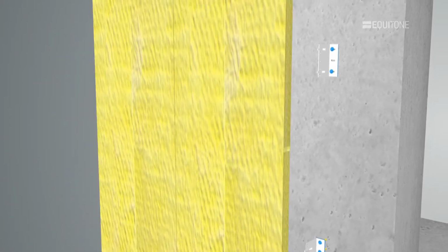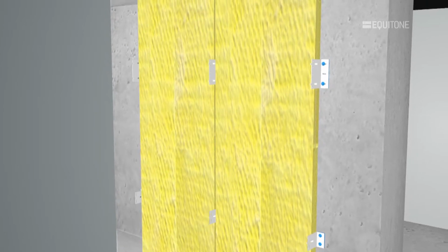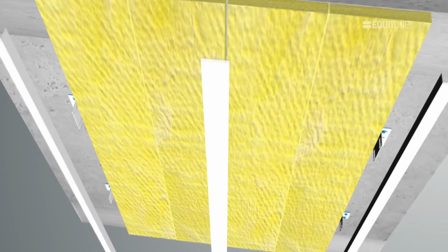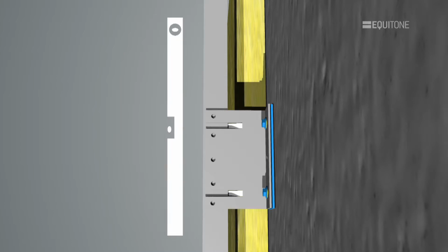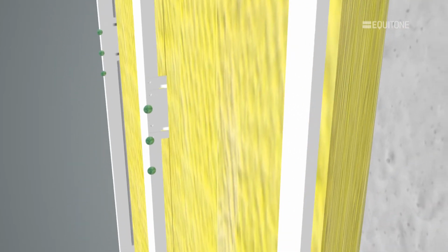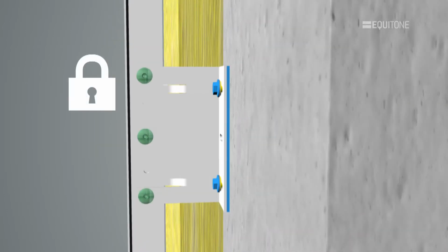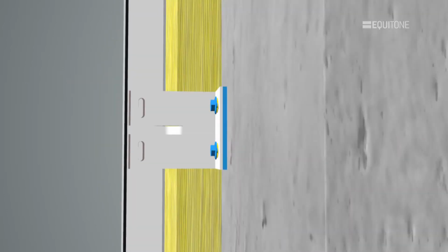Place the insulation against the wall. Using the clip on the wall bracket, insert the vertical T profiles behind the vertical panel joints and the L profiles as the panel's middle support. When final positioning is confirmed, fix the profiles. The wall brackets are arranged with fixed and gliding points.